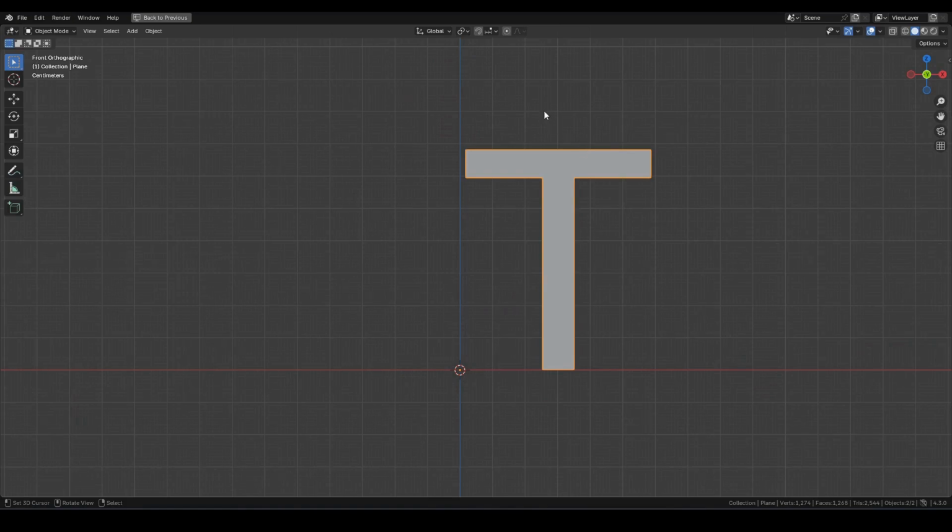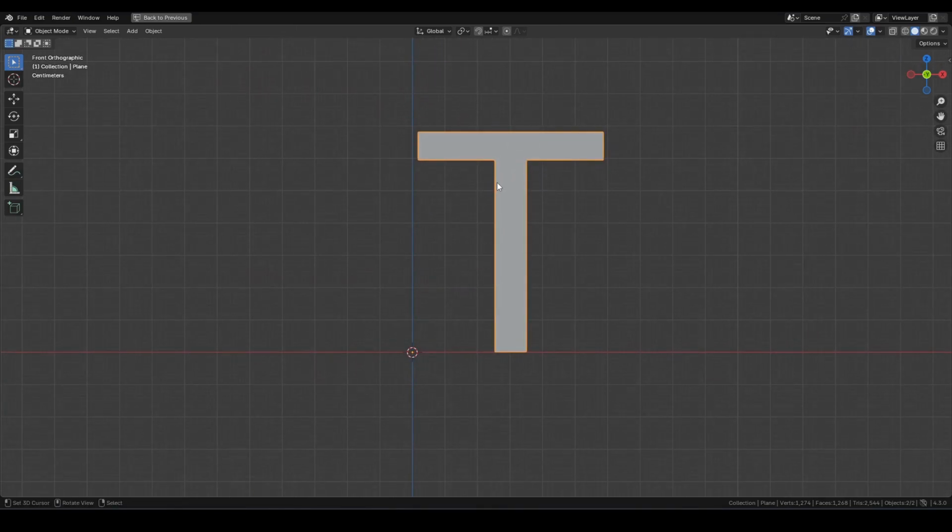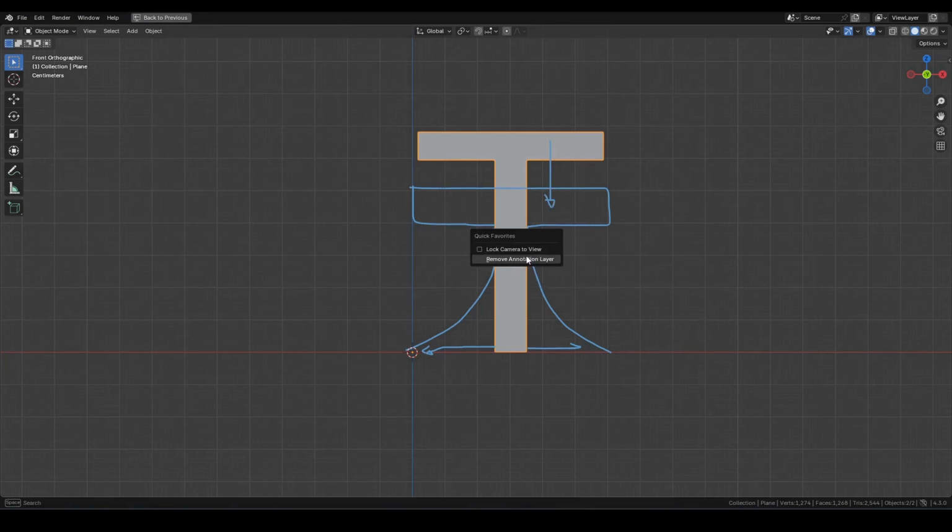For the 3D bounce effect, we'll separately construct the deformation and bouncing physics. Though it's not quite necessary to create a physics logic in geometry nodes, it is an easy and fun topic to cover. So let's start with deformation. We want to insert a squashing deformation when the letter hits the ground. The shape should look something like this. First, we'll spread the lower portion in XY direction. Then, we'll push down the top to create a squashed shape. Alright, let's get started.